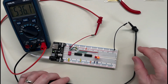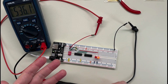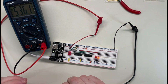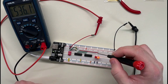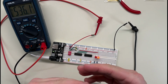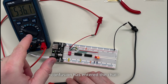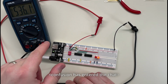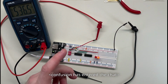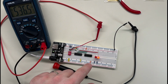Okay, so 536 millivolts across there, that's definitely less than 0.7 volts, so that counts as false. So I suspect then we can reduce the resistance and we would get a higher voltage across here, right? So I should be able to plop in a lower value resistor here, and maybe we can get near that 0.7 volts and see if the output changes.